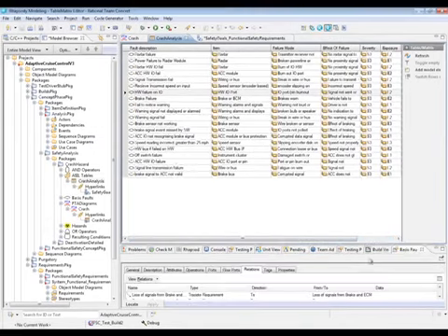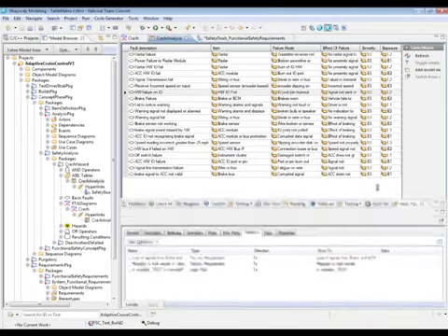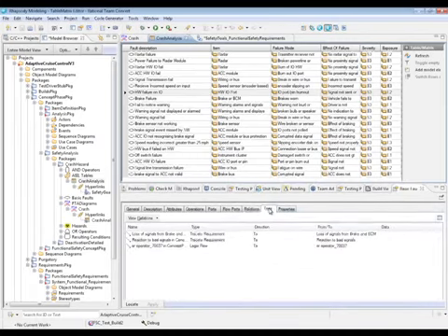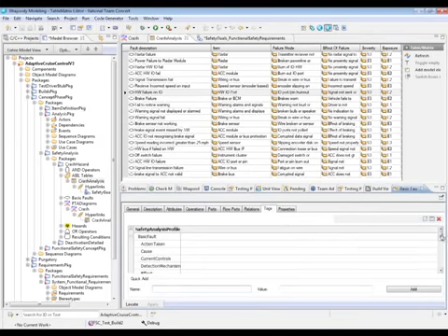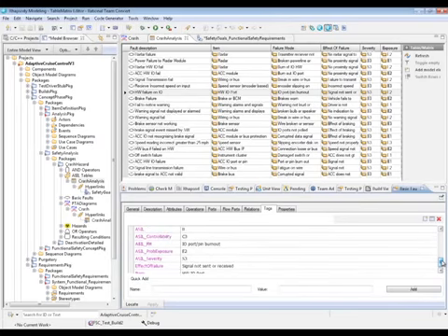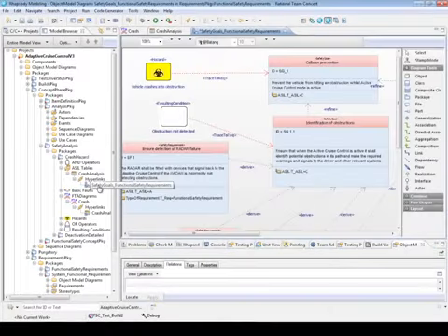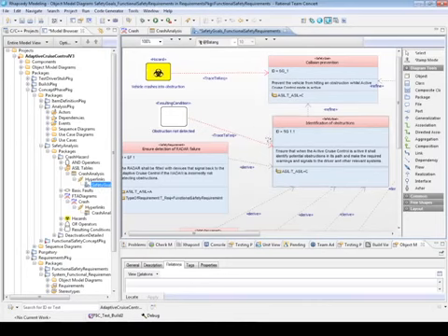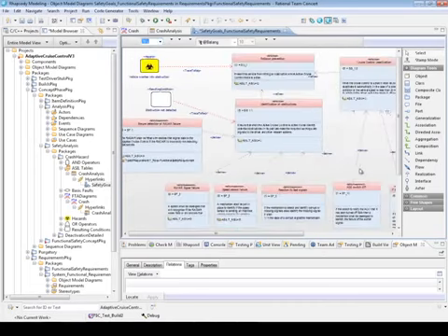This information is actually captured via a set of tags that are associated with a particular item. Here we can see the ASIL and its contributing attributes. From these basic faults, we can then start to derive safety goals and safety requirements. And this shows all the safety goals and safety requirements for this particular problem around the adaptive cruise control.